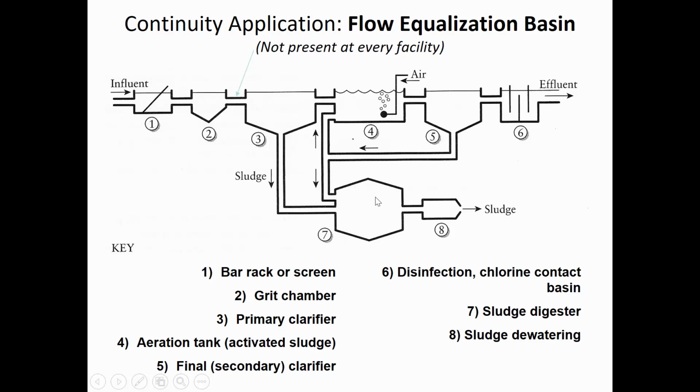One application I wanted to point out of this Reynolds transport theorem is the sizing of a flow equalization basin. This is a diagram of a wastewater treatment plant. And wastewater treatment plants are a little bit unique in that wastewater is generated at variable rates during the day because people use water less in the middle of the night than they do during the daytime hours.